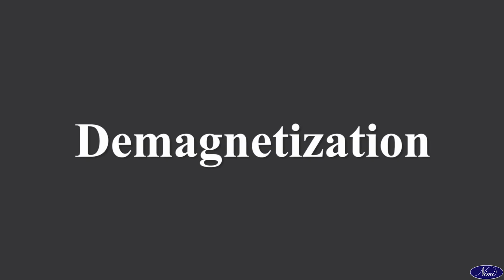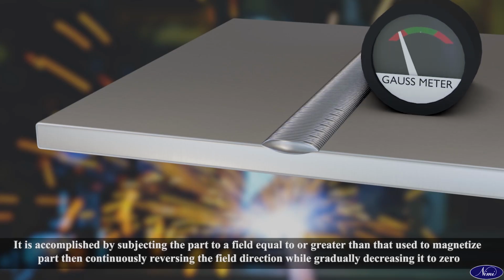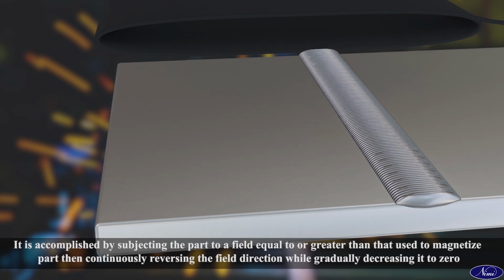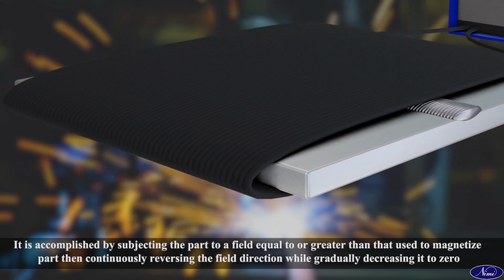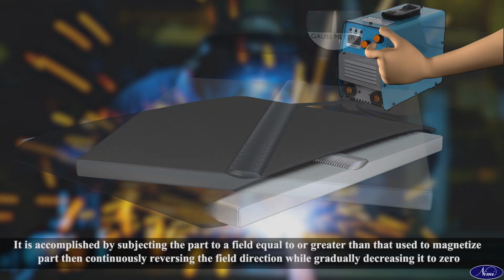Demagnetization. It is accomplished by subjecting the part to a field equal to or greater than that used to magnetize the part, then continuously reversing the field direction while gradually decreasing it to zero.